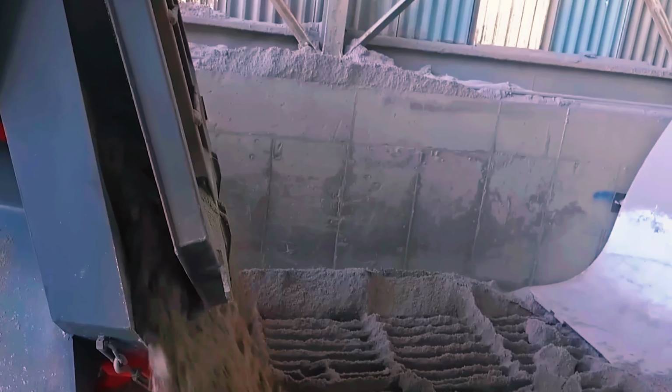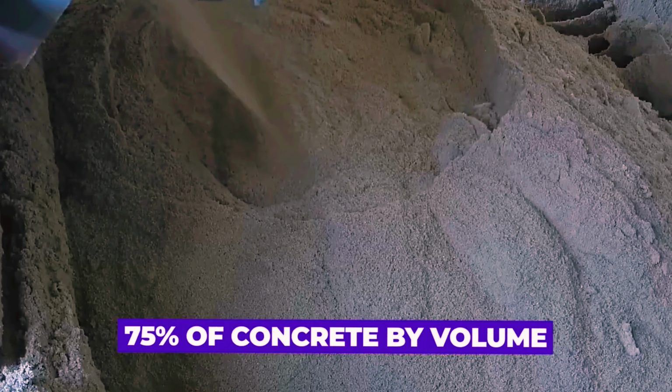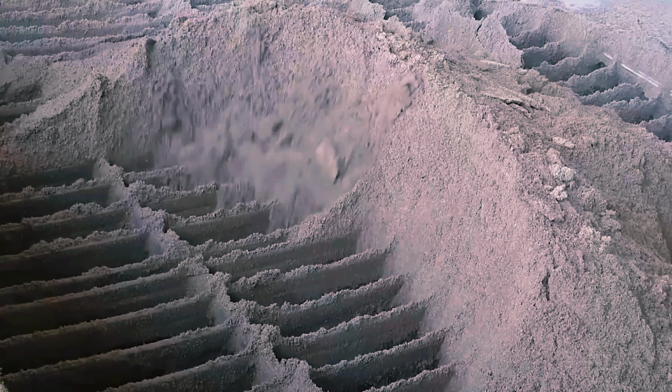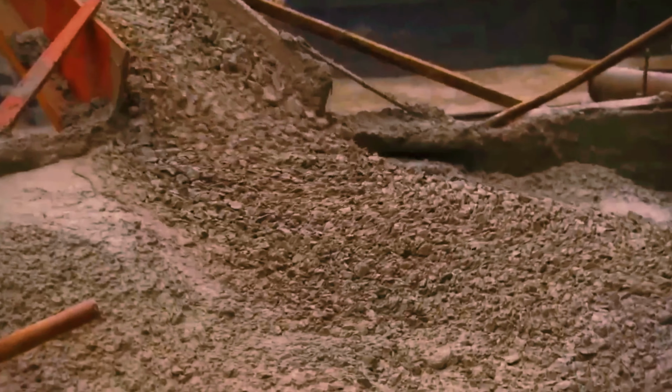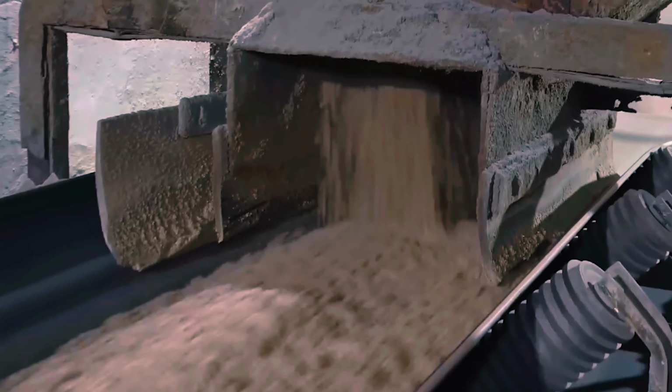The aggregate is the most important component of concrete, comprising up to 75% of concrete by volume. When it comes to composition, aggregate is composed of both gravel and sand. The sand is added so the spaces in between the gravel are completely filled, thereby giving the concrete stronger bonding and consistency. A well-graded aggregate, which is a balanced mixture of coarse and fine particles, reduces the requirement of cement, thereby making the whole process much more cost-effective.